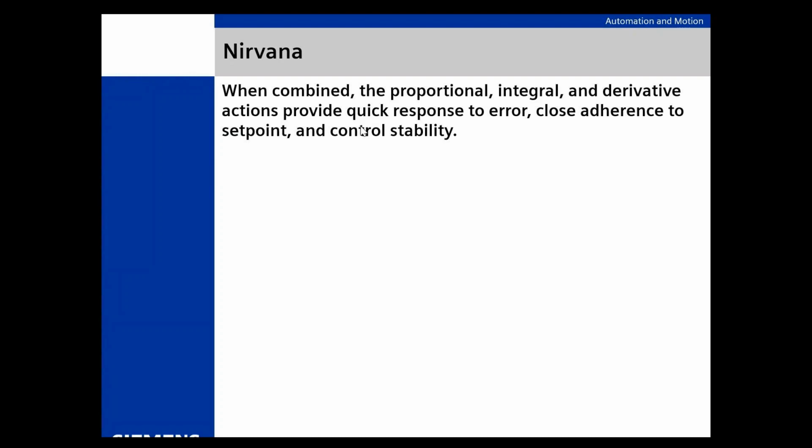So I want to see, and when it stops, I'll say, well, once it stabilizes for X period of time, 20 seconds, 10 seconds, however much time you can give me, add a little more, go up a half a pH now, okay? Hold, then a quarter, then an eighth, and that's kind of the way I do it, and it takes some tweaking. That's not going to be something that just happens, okay? But yes, the derivative is your friend in that loop because it's so hideously nonlinear.